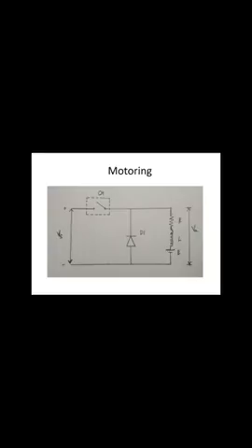Buck operation of the chopper is similar to the motoring action. Here both the voltage and current are positive, hence the motor rotates in the forward direction. When the switch is closed, the current flows from the source through the thyristor and the load back to the source. When the switch is open, the current in the inductor flows through the diode and the load, forming a loop.